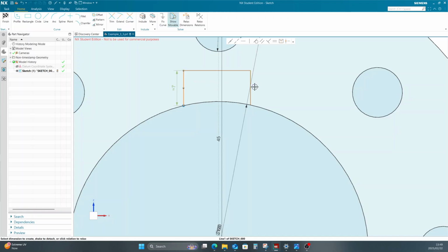Okay, and then just to make sure it's defined, you select both of them and say make vertical. So that ensures that those two lines are vertical. So that's just some optical illusion. If that line is over there, it looks like that one is going to the right, but actually it's vertical. Now I can specify the dimension, so I'm just going to click on that line, say that's 8 millimeters, and we can see from this that it's in the center there. So I'm just going to move it a bit so it can still move.